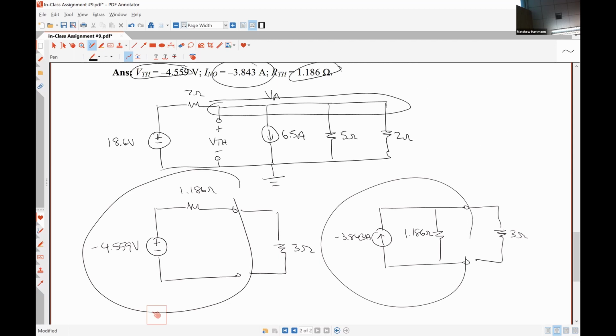The only real difference is that the Thevenin and Norton method will always work, while source transformations are limited in that you have to have a practical source to transform. So I just wanted to put that bee in your bonnet when you're working practice problems for your test.